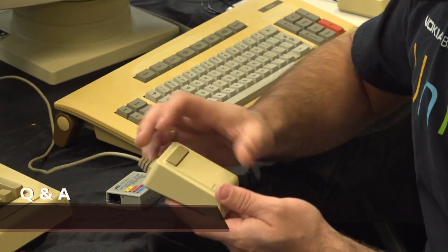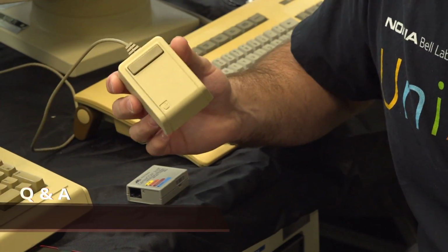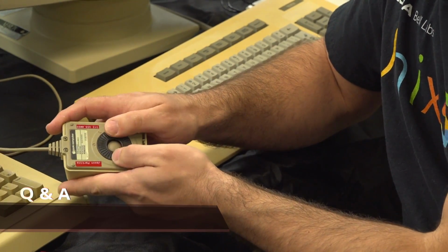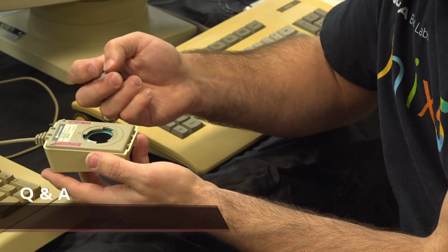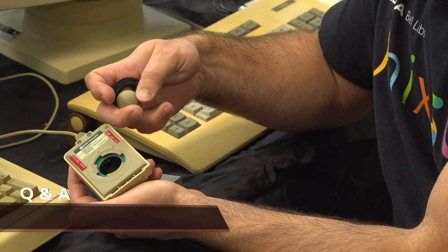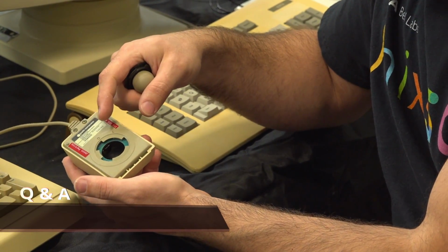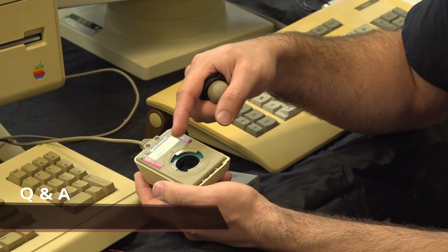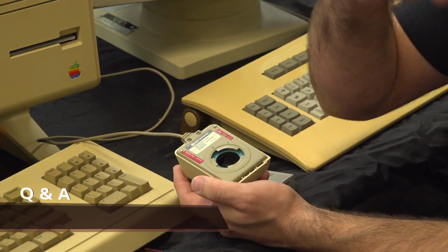The Apple mouse is made of injection molded plastic, has the ring that you can rotate to dump the ball out, and has plastic rollers on metal shafts with no bearings that go into an injection molded plastic frame, with LED opto interrupters.